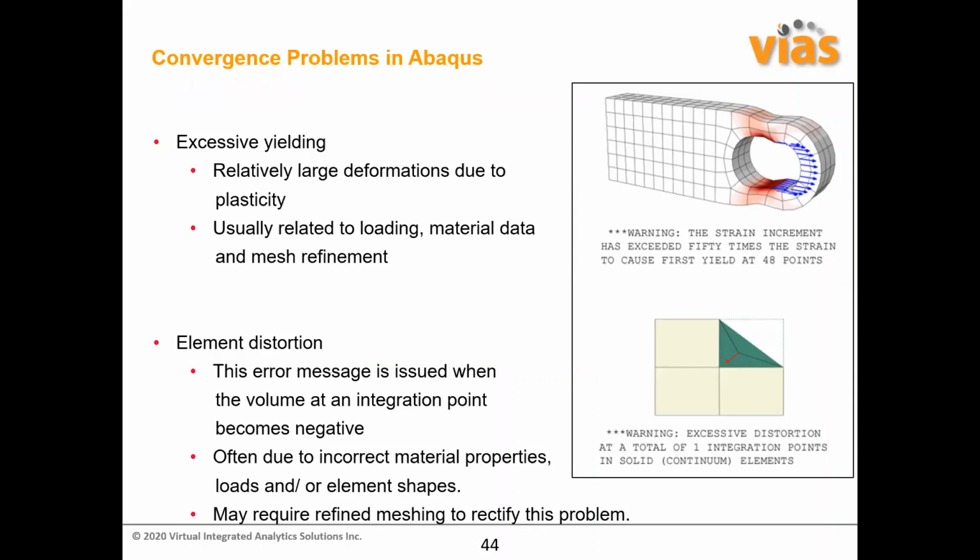Your green element is totally distorted, possibly due to some meshing error, or due to some partition. So you have to proceed fairly carefully from the part module to the mesh module, and make sure that your elements are correct, well defined, regular in shape, and there are no initial distortions in the elements, because generally these initial distortions may give rise to the problem.